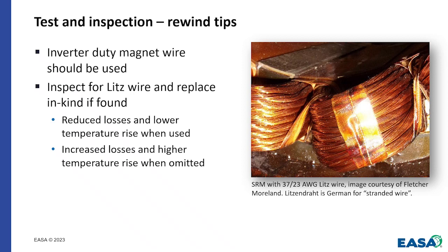The benefit there is we reduce those eddy current losses, which gives us lower temperature rise. If we don't replace it, we're definitely going to overheat, and your customer's going to be unhappy because the machine is going to fail. There's a couple of suppliers of Litz wire in North America, and there's a couple in Europe. Just a web search using your favorite search engine will find you those.